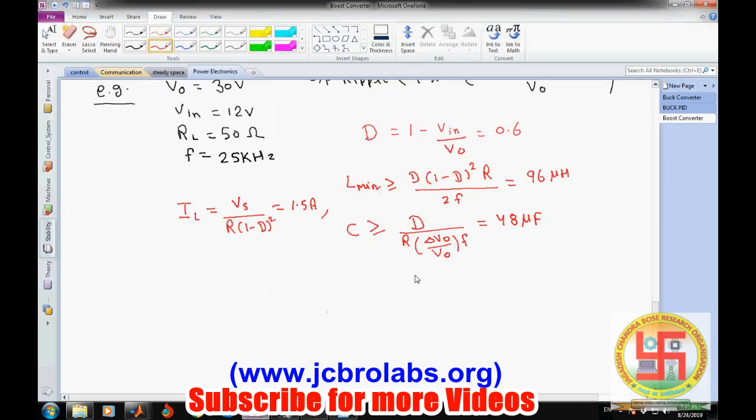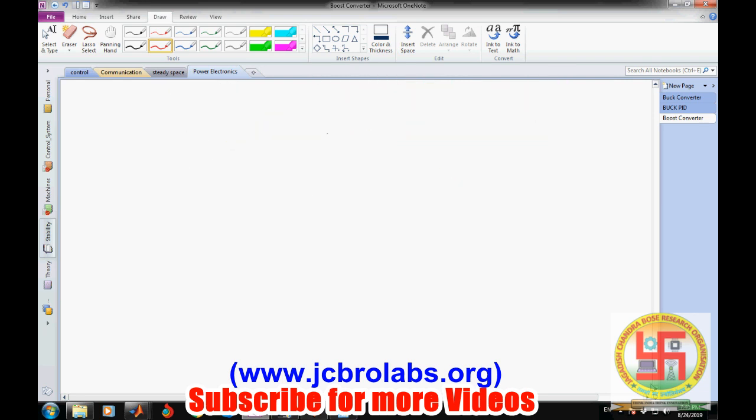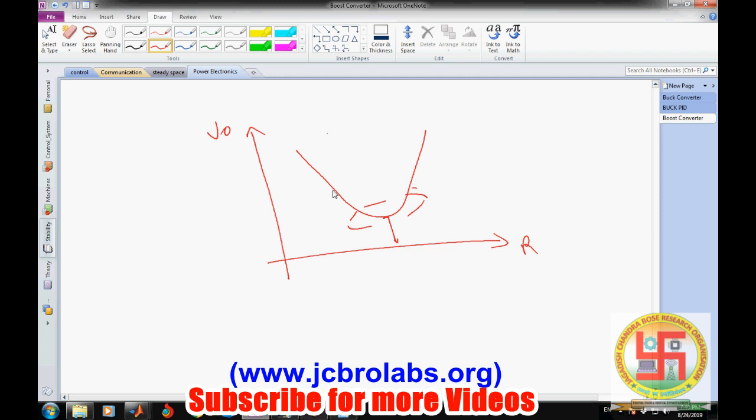If you try to make a plot of R and L, you can think of it varying like this one. Here we are increasing or decreasing the value of R, and here is the output voltage. So it is like this. Within this particular range, this R will work satisfactorily, but at this range, the output voltage may go beyond the safe limit. So this is how we need to reduce R.